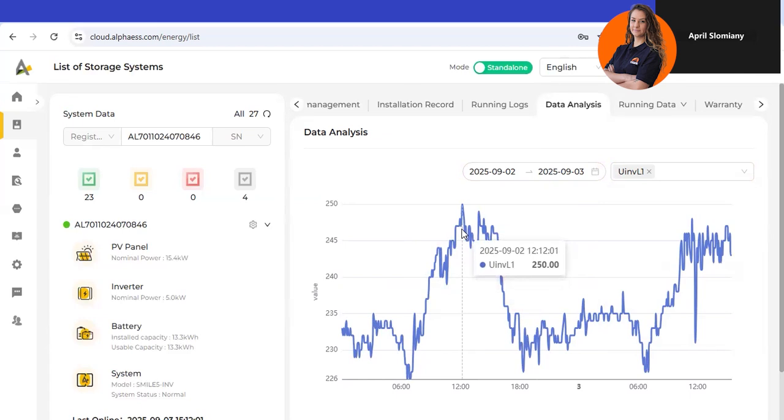This is a good one if you see sawtoothing performance on your solar. So very up, down. One moment it's producing 2 kilowatts, the next it's 5, then it's back to 1 kilowatt. Sometimes that's caused by high incoming grid voltage. Now, this is usually more of a problem in the summer when there is a lot of solar power being fed into the grid. If you do see that performance, it's a good idea to come and read this value and see where that voltage is peaking out.